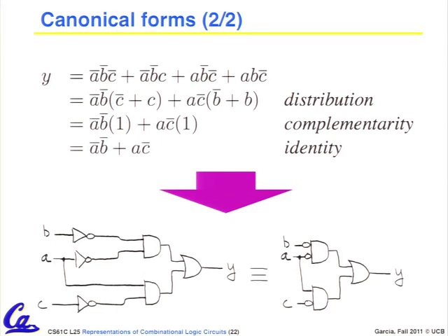Oh, these 2, the bottom guys. Oh, the bottoms are the same. Yeah, the bottom guy is just the bubbles moving. But the top guy to the bottom, if I decided to make this into circuitry, I'd have 4 AND gates, I'd have scattered inverters, and I'd have a 4-input OR. That's certainly much simpler. The bottom 2 are 100% the same. It's just ways that we draw them. I'm talking about the top to the bottom. But I didn't show you the picture for the top. Okay. All right.